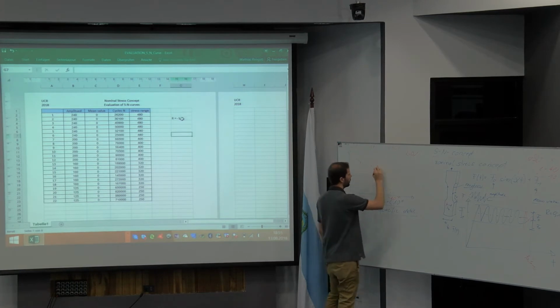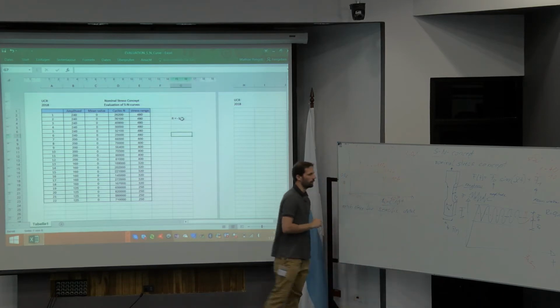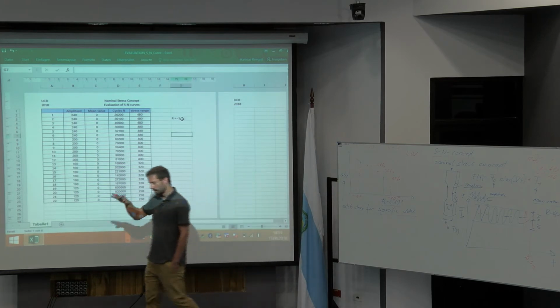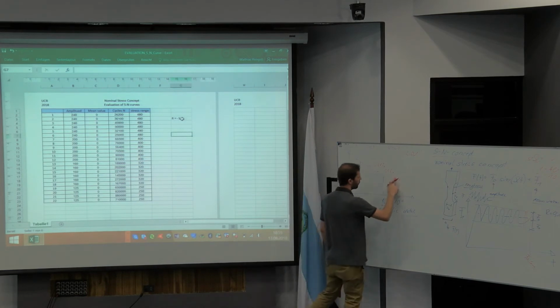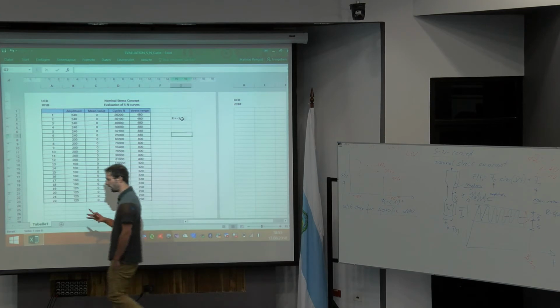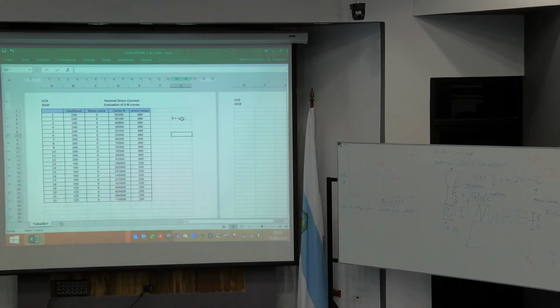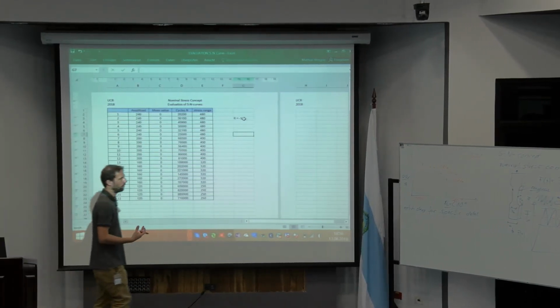The first horizon is here around 0.8 Fy, 0.6 Fy, 0.4 Fy. So this is some stepping of 3. But the steps are also somehow depending on the stress ratio you apply on your system during your testing.